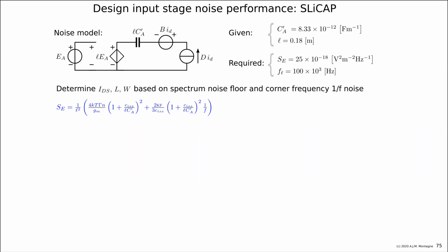It is not jumping into your simulator, trying something to optimize if there is no optimum. First, look at the expression, make a model that explicitly tells you what to do. This corner frequency has a minimum for Ciss equals the antenna capacitance.